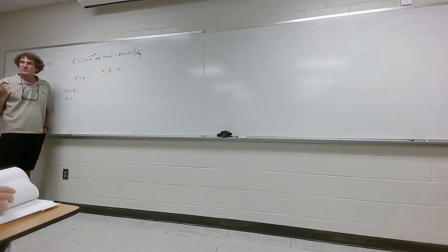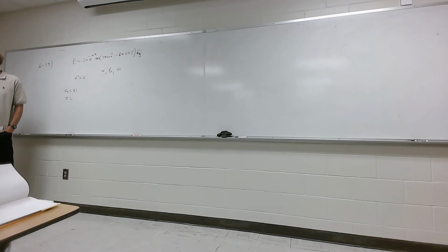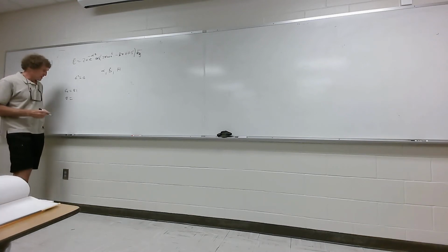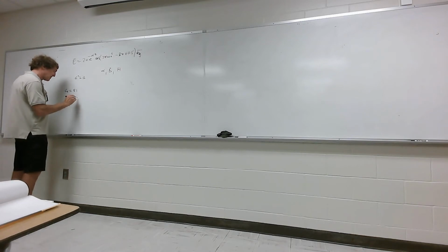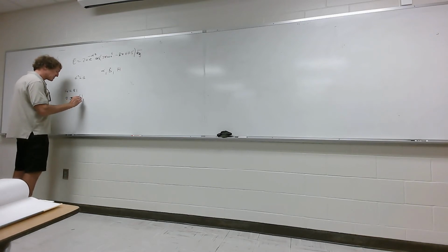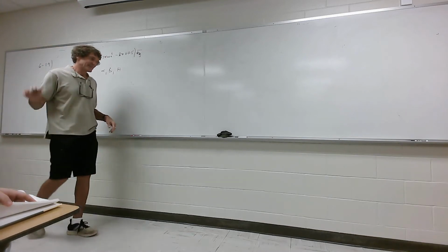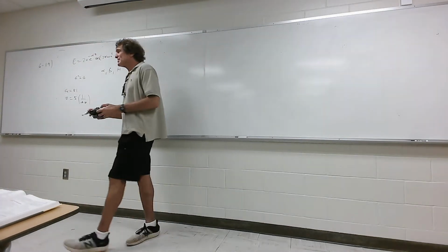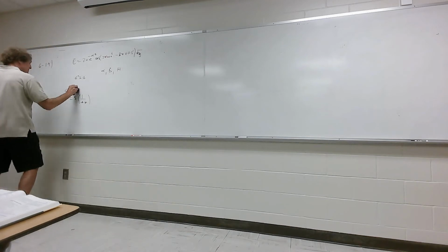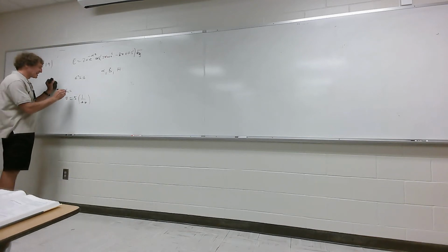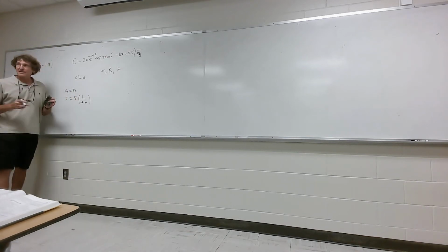You can't do these problems without these values, obviously. Sigma is 5, 1 over ohm-meter, or Siemens per meter. Is epsilon relative 81? It's 72. 81 is distilled water. It's frequency dependent, but I like 81 because the square root is easy. All right, we'll go with 72.